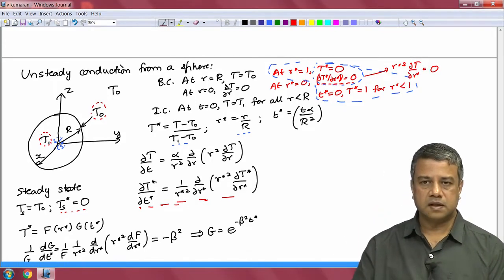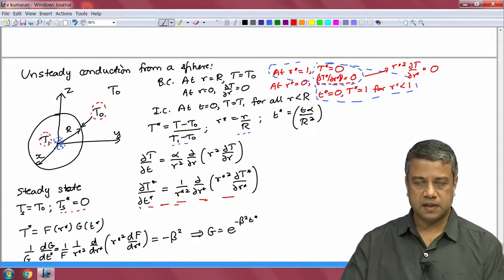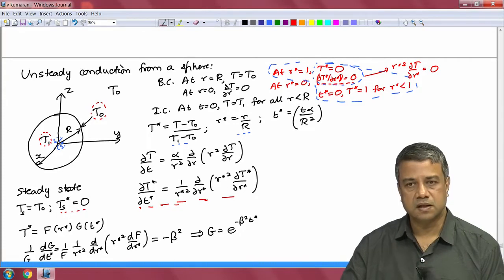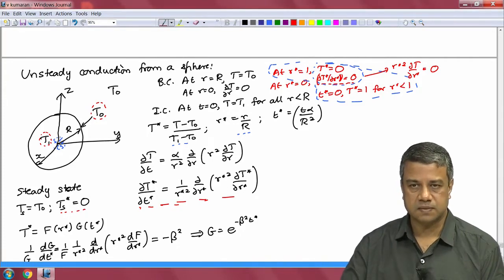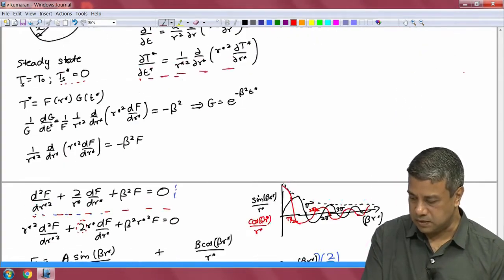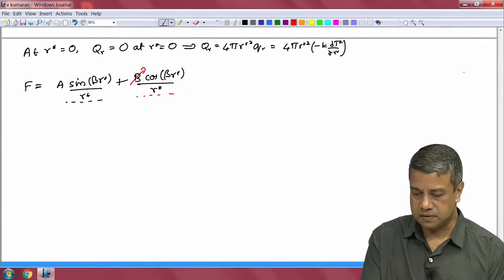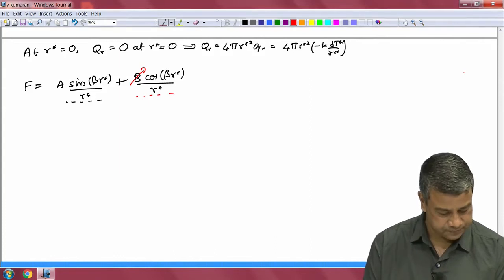Okay. This comes from the physical requirement that the flux times the surface area has to decrease to 0. There is no heat source there. It does not mean that the flux has to decrease to 0. So, kindly note that correction.